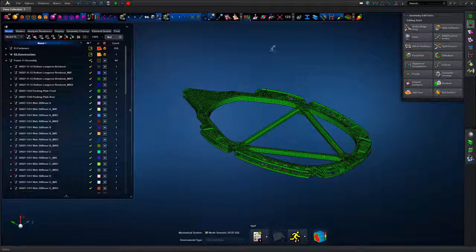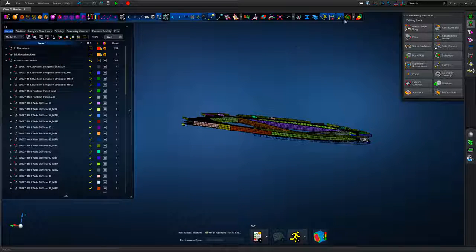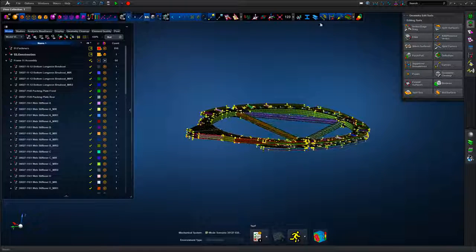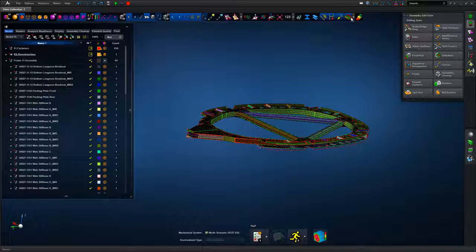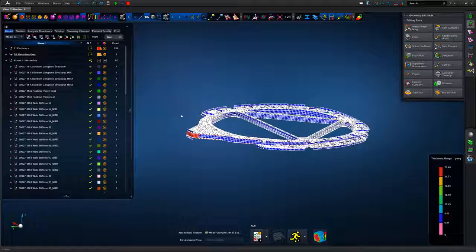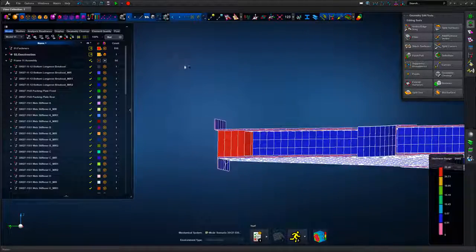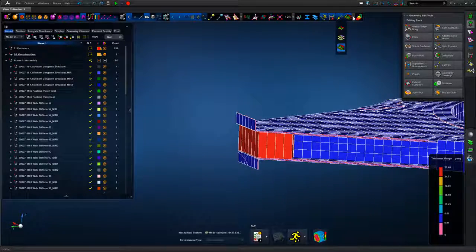Again, just running through this pretty quickly in terms of the demonstration. Once we've got those mesh edits done, we can check the shell thickness definition by putting the surfaces on and looking at the 3D representation of shell thickness, working its way through this set of property sets. We can see we've got one shell which is very much thicker than the